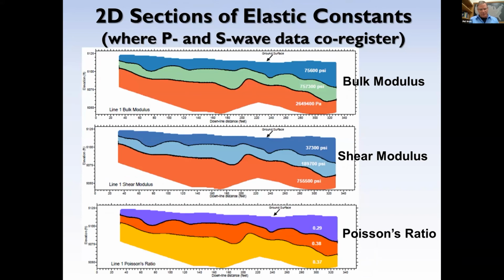The last slide I share with you today is an MSE wall project that I did for a former friend of all of ours, Kamisa Rami. And we actually decided what we wanted to deliver to the engineers was not a shear wave velocity or a P wave velocity cross-section. I've yet to see a designer work in that space of velocity. So when we assign generalized layers and we get unit weights, it isn't hard to go to 2D sections that are just in modulus, as long as you understand it's not deformation strains, it's down in the elastic strains. I know that this information can be used in a much better sense. This is where I believe we'll be going much closer in the future than further for seismic measurements.